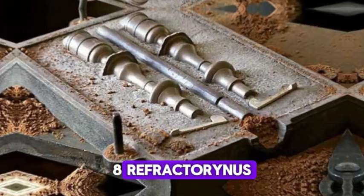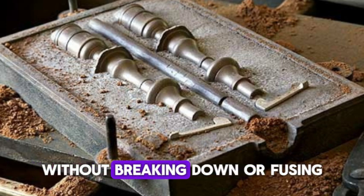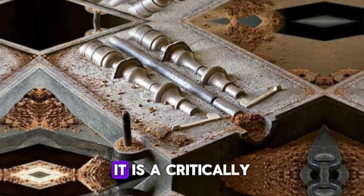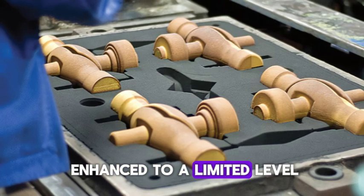8. Refractoriness. Refractoriness is described as the capacity of molding sand to tolerate high temperatures without breaking down or fusing, therefore helping to produce good casting. It is a critically important property of molding sands. Refractoriness can only be enhanced to a limited level.